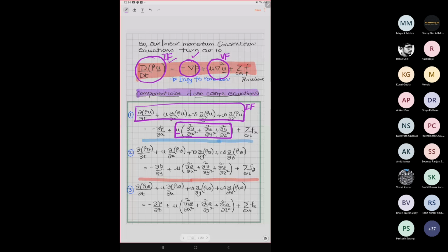And it's always an important question whether inertia force is large or viscous force is large. People usually compare inertia force to viscous force. That technically people call Reynolds number. That was done in the 19th century. Any turbulent motion, wiggling, jiggling, chaotic kind of motion happens when, at your equation level, your inertia forces become so large compared to your viscous forces that naturally fluids start getting distorted.